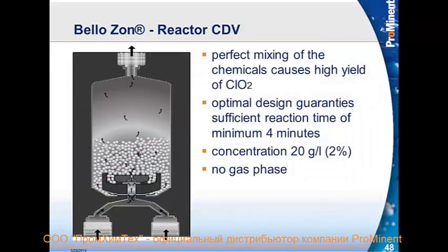This is the inside of the reactor. As I mentioned, a 2% solution inside. There are mixing beads inside to help mix the chlorine dioxide gas with the water solution to create a 2% solution. Once again, there is no gas phase in here. Everything is an aqueous solution.